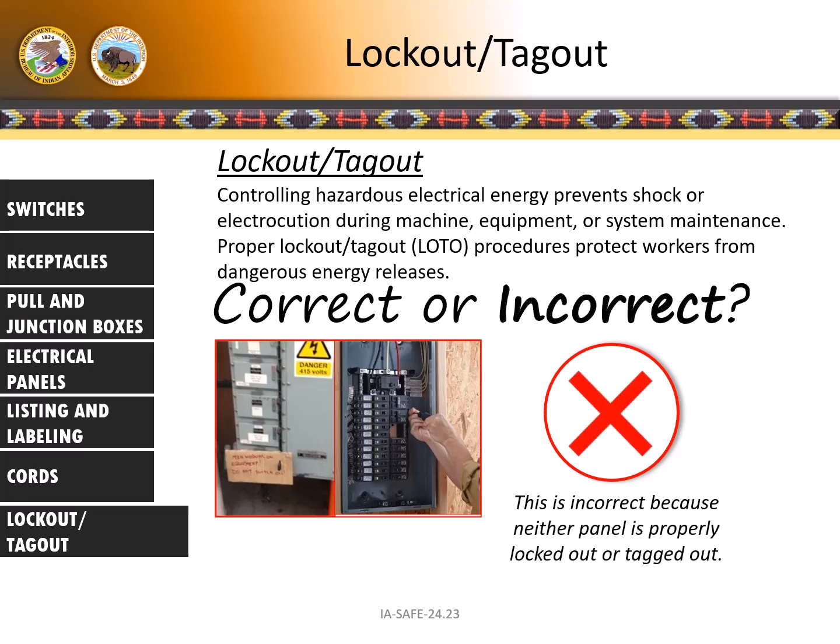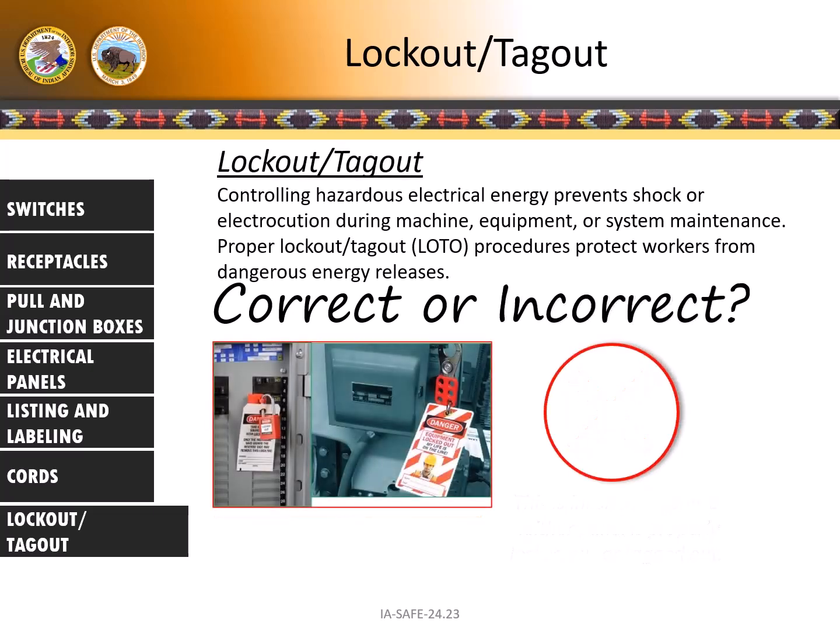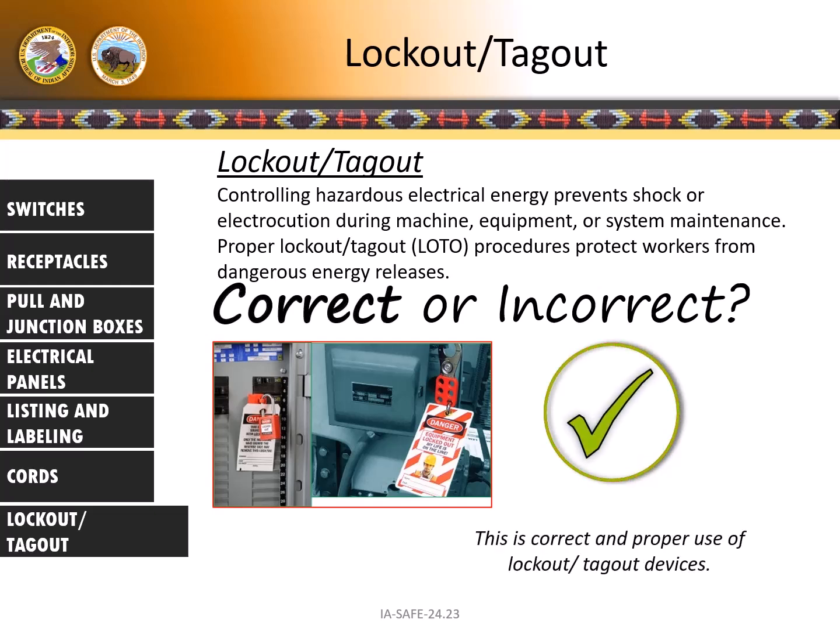This is incorrect because neither panel is properly locked out or tagged out. Is this example correct or incorrect? This is correct. Improper use of lockout-tagout devices.